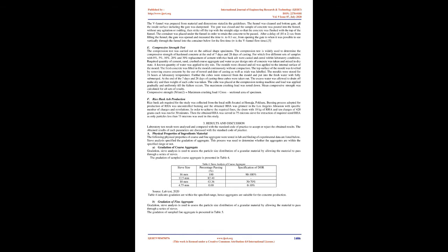The container was placed under the funnel to retain the concrete that passed. After a delay of 10 plus or minus 2 sec from filling the funnel, the gate was opened and the time TV was measured to 0.1 sec, from opening the gate to when it was possible to see vertically through the funnel into the container below for the first time. TV is the V-funnel flow time.